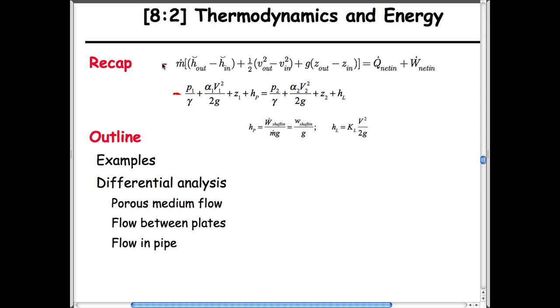We can write it either in terms of enthalpy, where this is basically defined as internal energy plus pressure over density in this particular case, and is defined again between upstream and downstream in some kind of stream tube that we know. And just for our own edification here, it has to be written between upstream and downstream. So the velocity is always a streamline velocity, as you'll remember.